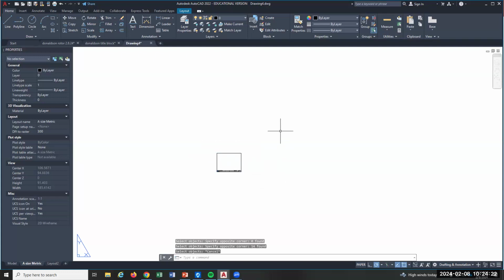The other window is this one. Everyone, did you know that one existed? The green one? That's a crossing window. Anything it crosses, it chooses. So when you get used to these windows, you'll never use that little pick box again. You'll just use these windows. Like cross it and you grab it. Okay? All right.